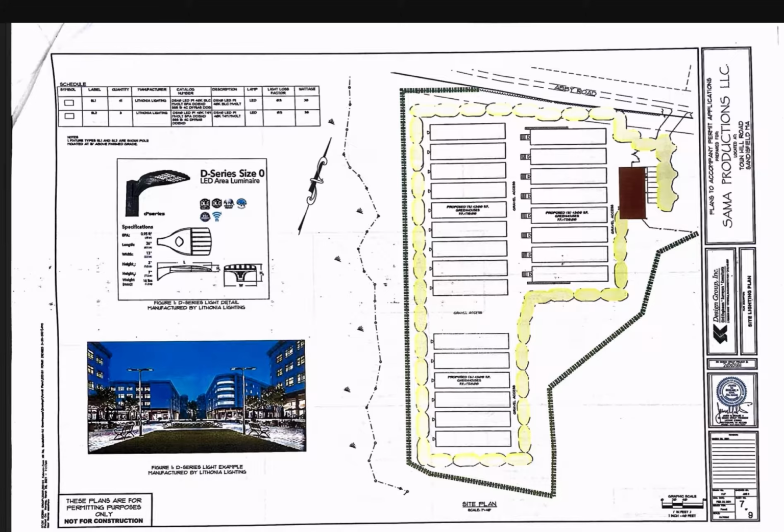It's up against the state forest, and it's generally a greenhouse use, but will be cut into the hillside. So if there's any potential for noise, it'll be blocked by the natural grade. There's about a 15 or 20 foot cut in this back section. So we're cutting the ground down and terracing these through what I call greenhouse area 1, 2, and 3. So each of these are on their own little plateau to kind of step with the earth to minimize site work and balance the earthwork. But that's generally our feeling.